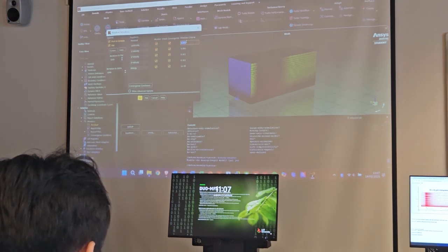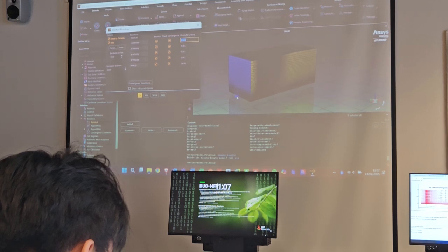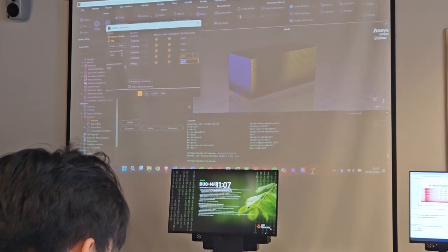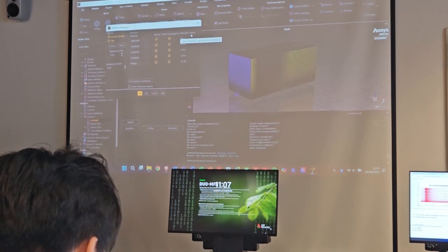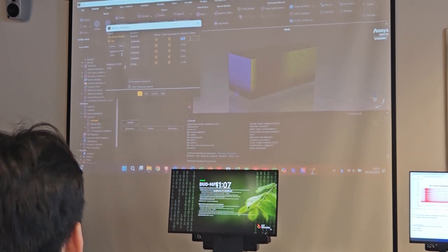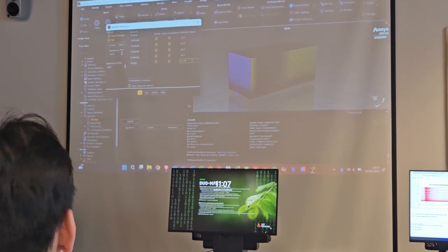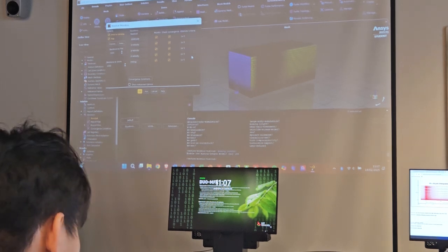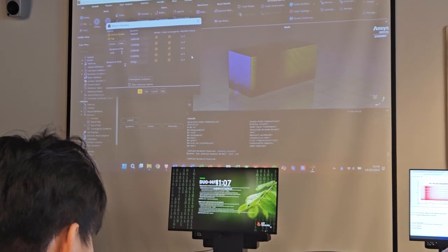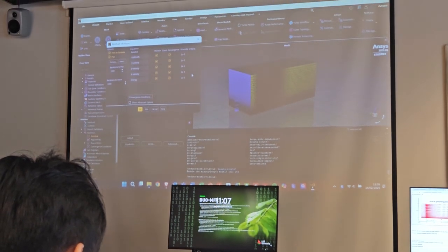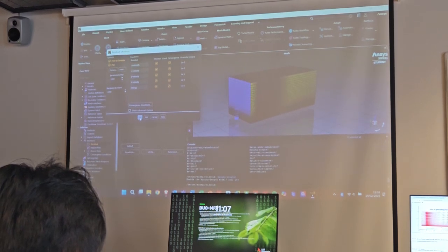Now you don't need to know exactly what they are for this course. You can just trust me somehow and set them to a low value, 10 to the power of minus 5, it's fine. So I set all of these to this value. So I can say that when the residuals of the solution are that low, then the solution can stop because I have a convergent solution. And okay.